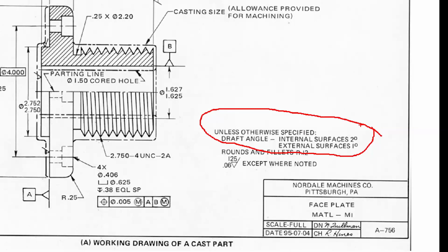And anytime you have a hole that's perpendicular to the parting line, you can just put that hole in the mold and it molds and everybody's happy, right? But if you have a hole where the axis of the hole is parallel to the parting line, then you have to do some magic in the mold to make a slide come over there and lock in and make a hole. But that's a little bit more expensive, a little bit more challenging. But that's what the red piece is, a little slide that as the mold opens, the slide comes up. As it closes, it goes down.